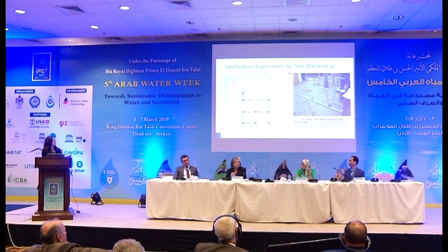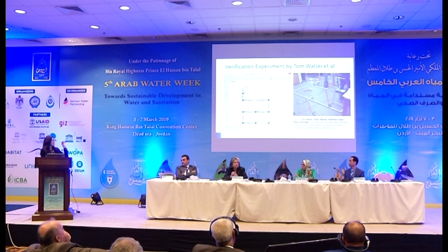They varied the pressure head at the supply source, which is the tank at the top of the screen, and they simulated the orifice at outlet B and outlet C by throttling globe valves at those 2 outlets to simulate the different sizes of the nozzles at the customer connections.